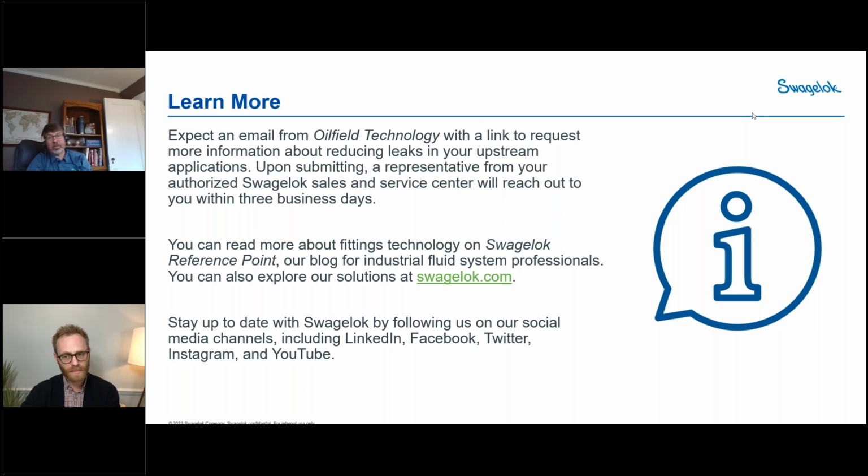But for, I think the question you said was a packing. So for a stem packing for hydrogen, we would want to look at using as dense of a fluoropolymer as we can. A lot of times hydrogen is best with nylon, I believe, if I remember correctly. And you would want to use a very large packing design. So when looking at a valve handle packing, you would want to see how large that packing is. You would want to have it be as large as possible. I think I would recommend nylon, but we might need to do a little research there and we can get back to that person. Great, thank you, Doug.